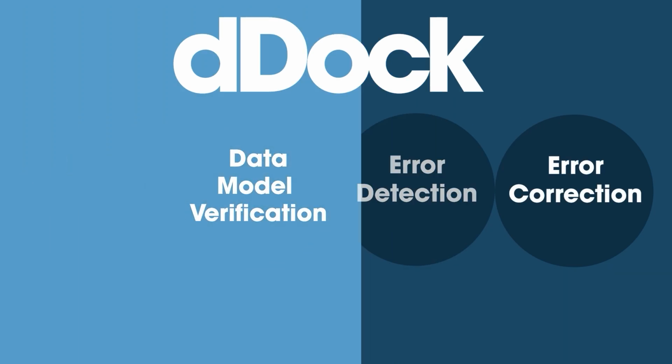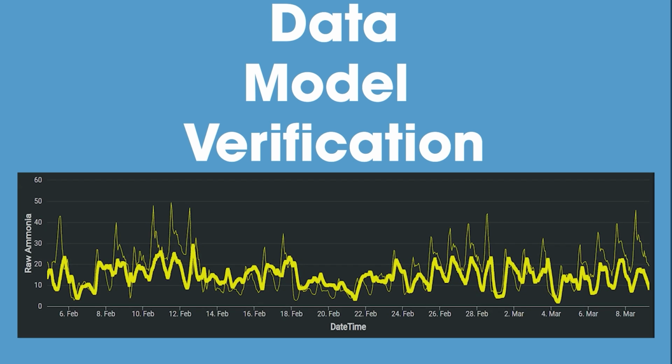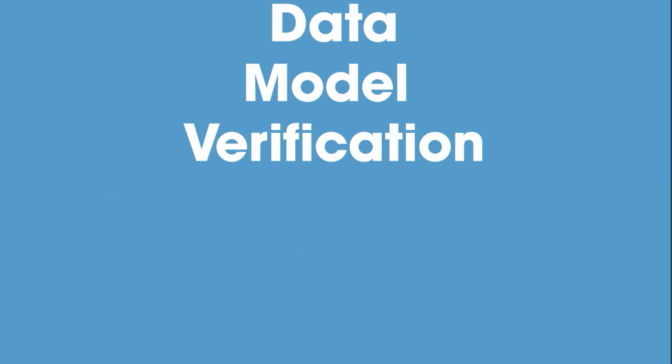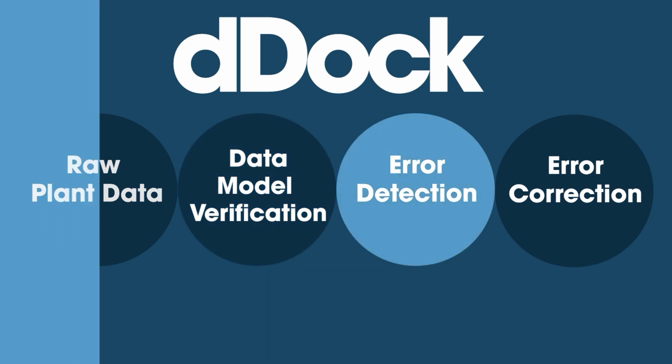Anytime raw data is analyzed or manipulated, it is important to verify that those actions are appropriate. That is, there needs to be continuous verification of the raw and alternate values. Traditionally, this verification might take the form of control charts or comparisons to reference values to signal problems. More advanced approaches involving principal components or similar analyses can also be used to indicate if the raw data is deviating from its normal operating range or if the alternate value is appropriate.